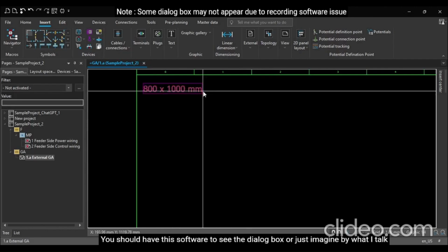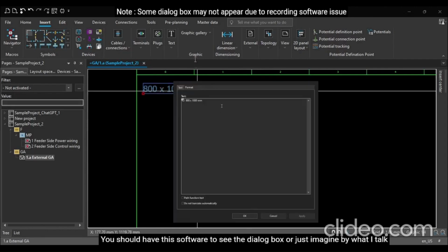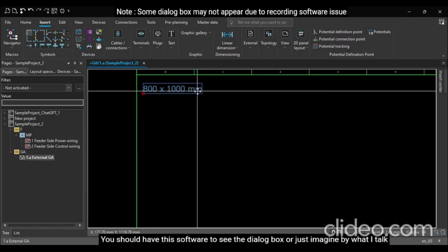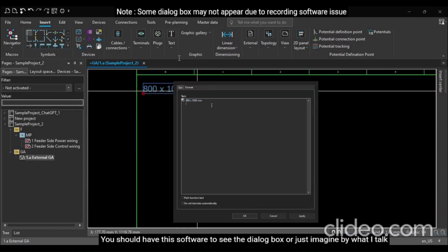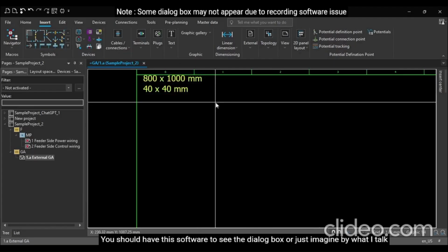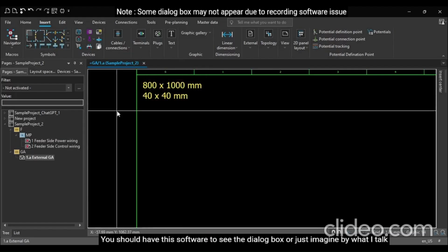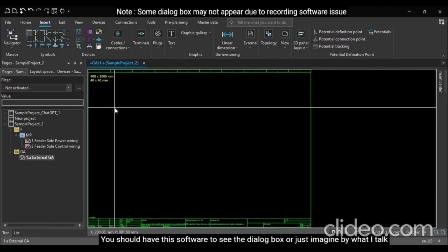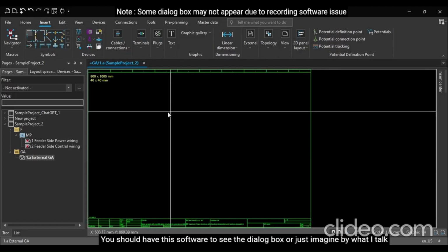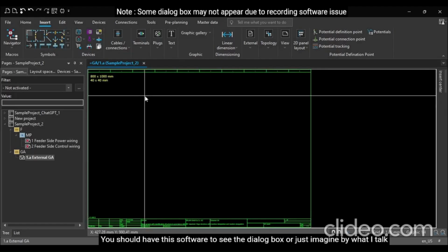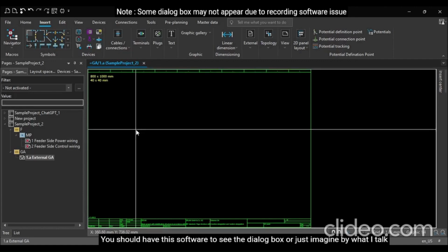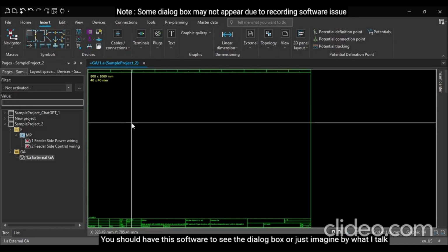Okay, what more we have to do is we have to apply cable duct. So cable duct will be 40 x 40 mm. This is just for designing. Else what we'll need, we'll input it here. Okay, so I'll place alt 3, and now what we have to do, we have to insert a rectangle which is a graphic.